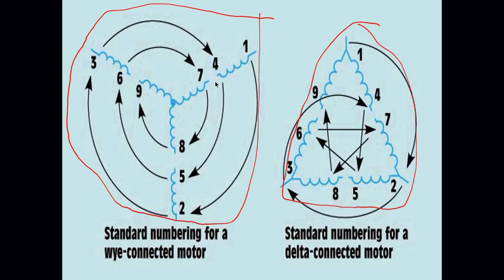So you might have to connect power to 1, 7, 3, and 9, 2 and 8, or you might be told to connect 6 and 9 together, 4 and 7 together, 5 and 8 together, and connect your L1, L2, and L3 to just my 1, 2, and 3. That's all very important. It's on the motor label. Makes a big difference in voltages.